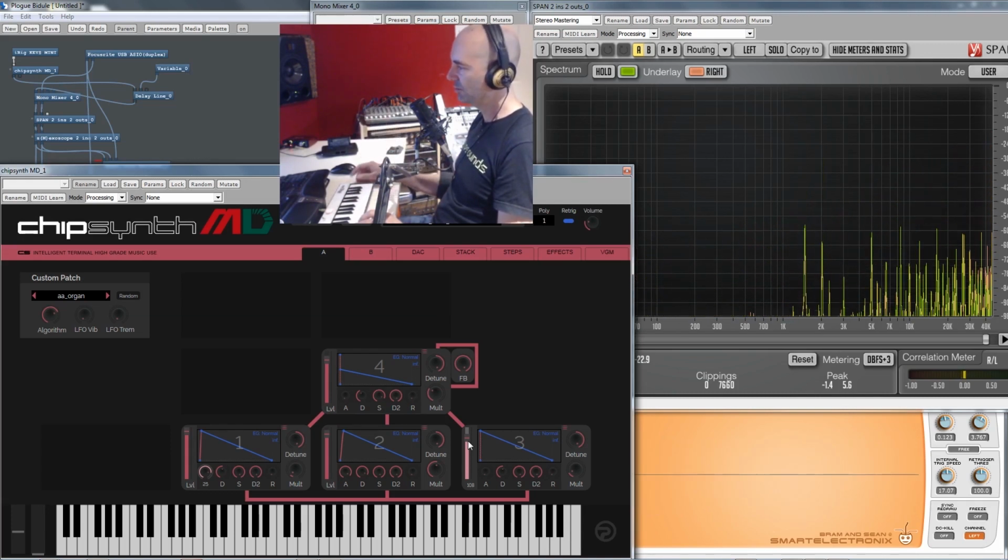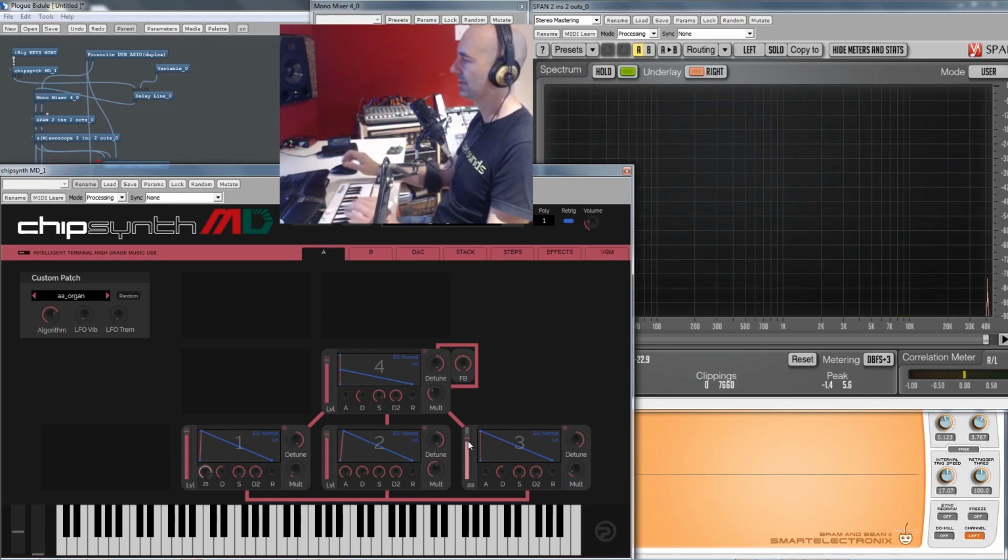See, the spectrums wouldn't match and wouldn't sound remotely similar if it weren't for the fact that we emulate the chip at 53 kilohertz, well, each channel at 53 kilohertz. It's not that simple because we do the multiplexing as well.